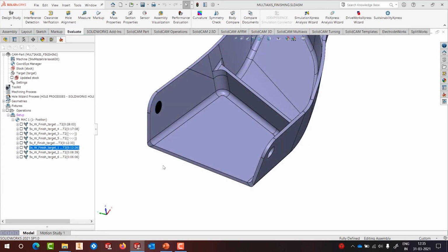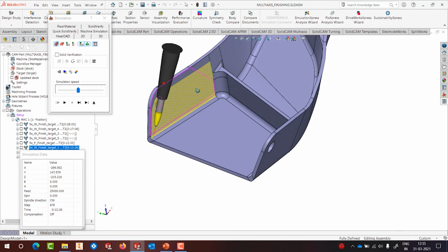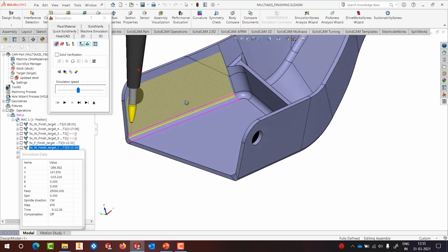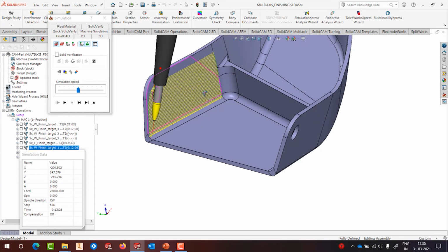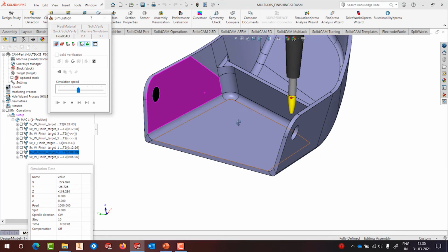Once that is done, it generates a pretty nice looking toolpath using the oval form tool, where it maintains a constant contact, and depending on the collision geometry, it also changes the direction or the tilt, but it will always have the contact point on the barrel shaped or barrel form area only and not on the tip. So using this method, I have also done this region here.